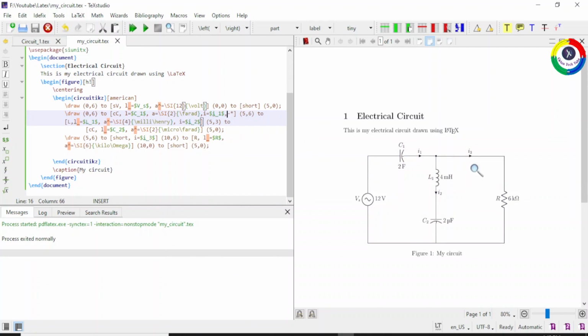You can also add a symbol for a voltage drop on a particular circuit element. For example, we can add a voltage drop VR here with a desired polarity. For example, let's add a voltage VR, comma here, small v equals, enclosed with dollar signs, capital V underscore capital R. I can remove this label in this annotation and add a dollar sign here with a power superscript.